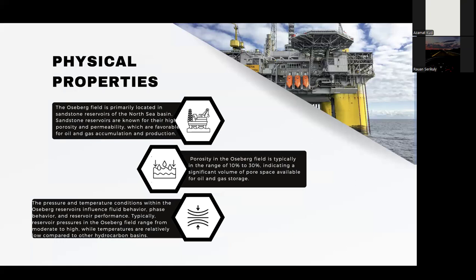Reservoir pressure in the field declines on average 100 to 200 PSI per year due to fluid production. In this field, they use management techniques such as gas and water injection to mitigate the depletion effects and optimize hydrocarbon recovery. Also, the adjustment of injection rates is performed to maintain the reservoir pressure within the optimal range of production.